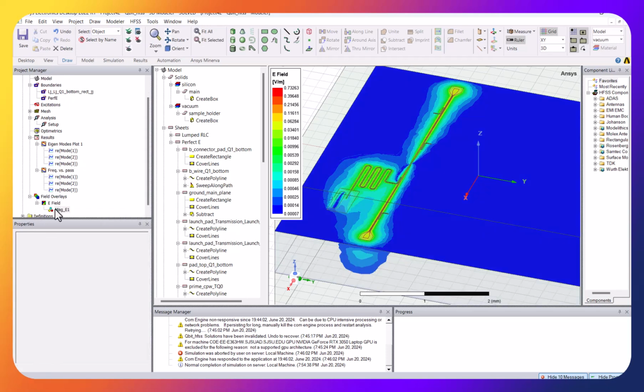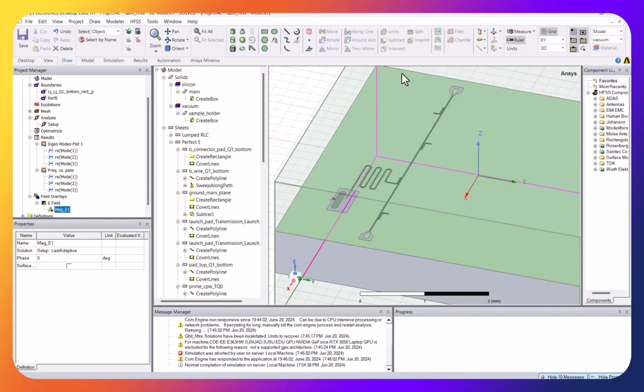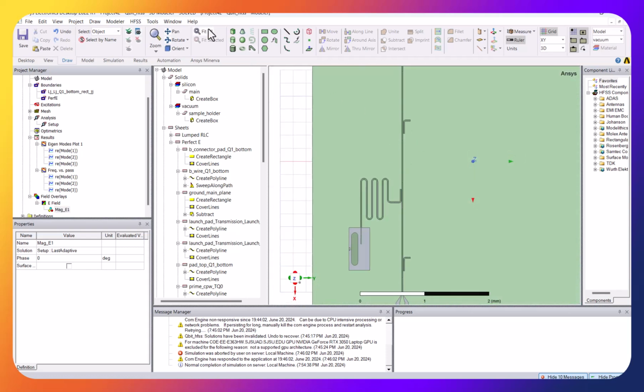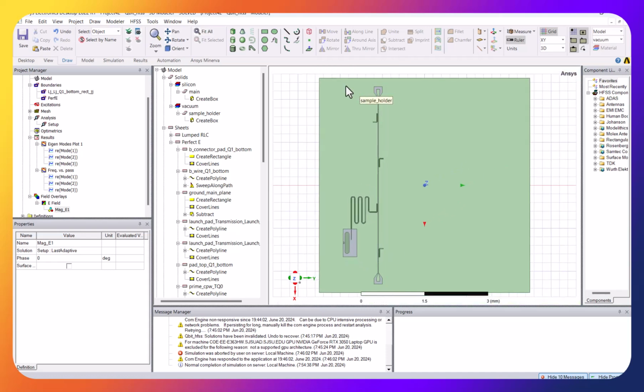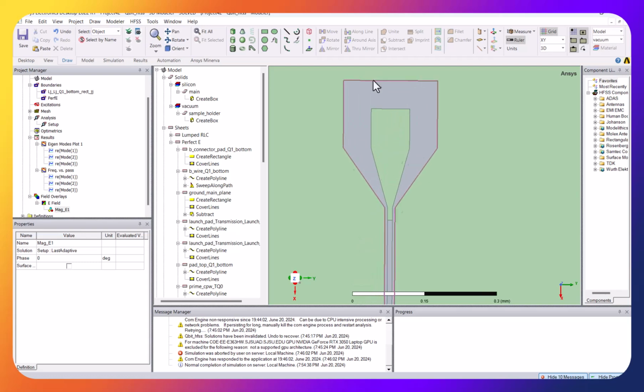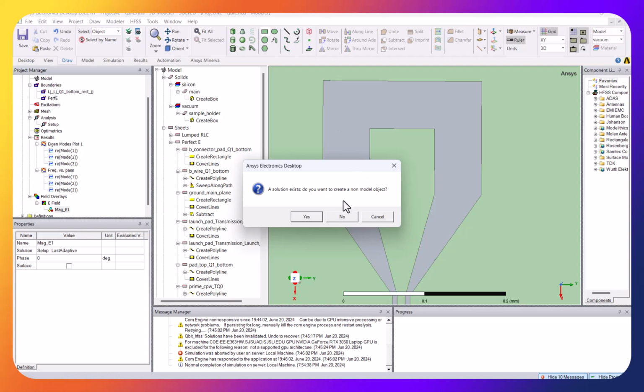Right click, plot visibility, remove it. Now, in order to get the Q, I need to couple it to the outside system, and what we will do is add an RLC port. So I zoom into here. This is the input of the 349. Then I will try to add a square. I do want to add something, not just a lumped model.